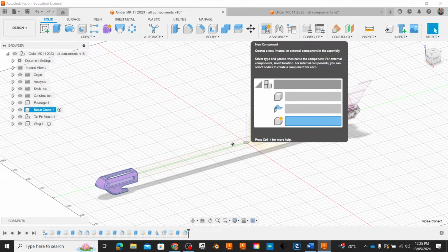Okay, it's very hard to spot where the NACA profile goes, but it always goes to the origin. And for some reason, it doesn't always go to the position that you want it to be in. So under Sketches, if there's other objects getting in the way, you can just make them invisible. We see in this case the airfoil sketch has gone here. Cool.